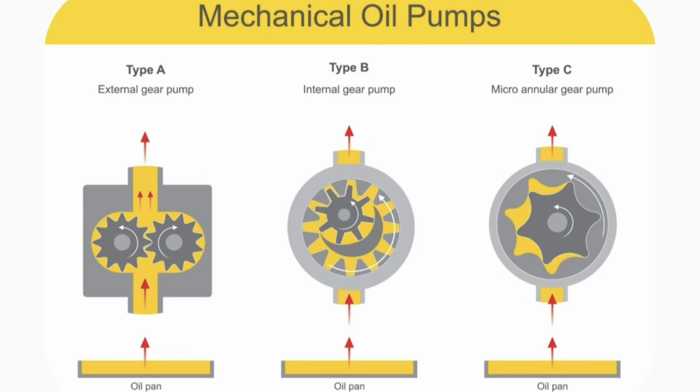2. Vane pumps, medium pressure and quiet. Vane pumps feature a slotted rotor offset inside a cam ring housing. Slidable vanes extend outward via centrifugal force or spring pressure. Fixed displacement vane pumps: as the offset rotor turns, expanding cavities between vanes draw fluid in, while contracting cavities push fluid out through the outlet.